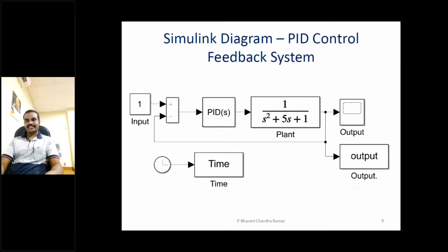And now in the next case, I have replaced this proportional constant Kp, or only the gain block, with PID control. And the plant is the same. I will show you how to do this one, and I will send you the YouTube link as well. So this is the PID controller, and 1 by s square, this is the plant. This is the new plant because it has another plus one term, and this is the PID controller. Once I use the PID controller, my desired specification is that the steady state error should go to 0 in whatever be the case.